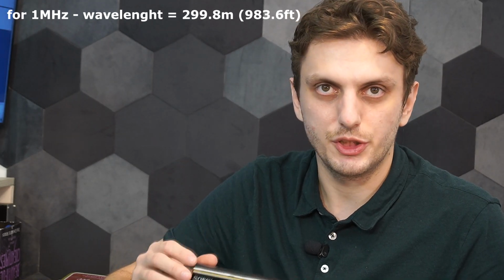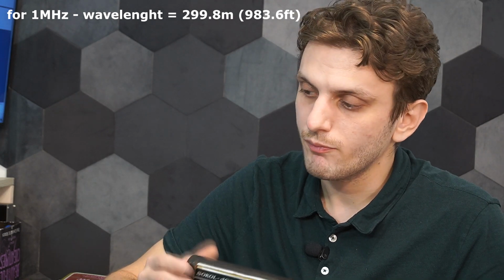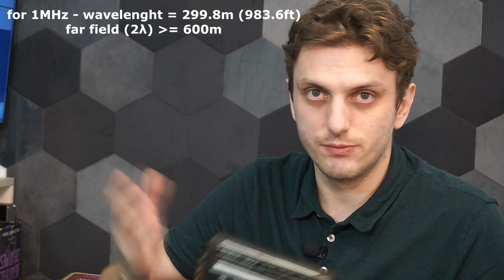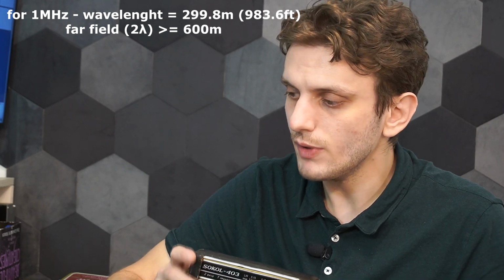But considering that we are working at very small frequencies, 1 MHz is a frequency at which the wavelength is very, very long, radiating electromagnetic radiation on a short distance is virtually impossible. So the only other way we can take the signal from our circuit to the radio would be in the form of either electric fields or magnetic fields.